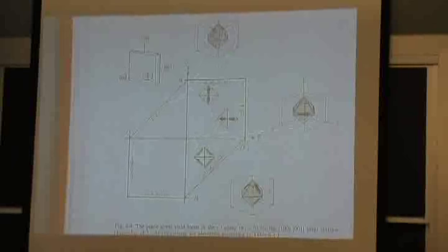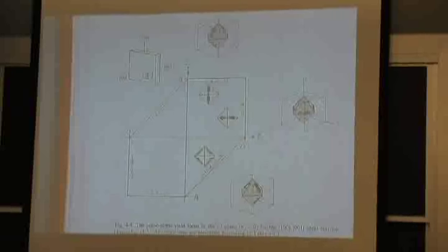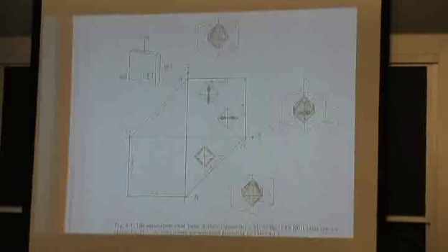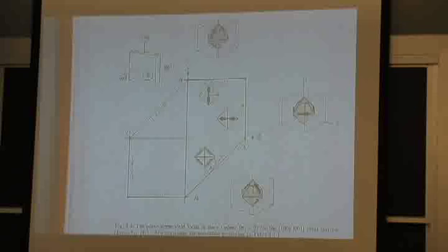If you're pulling in this direction, just a uniaxial tension, your slip systems will be these four planes in these four directions, and you have symmetry top and bottom, so it's not really 8 slip directions. It's basically this plane down here is the same as the back plane up there. This plane here is going to be into the board underneath. We don't have to get into all of this, but if you followed that, some of these 8 faces are not all independent. There's only 4 independent planes here, okay? And there are 4 independent directions. That's 4 slip systems. That's not 5.